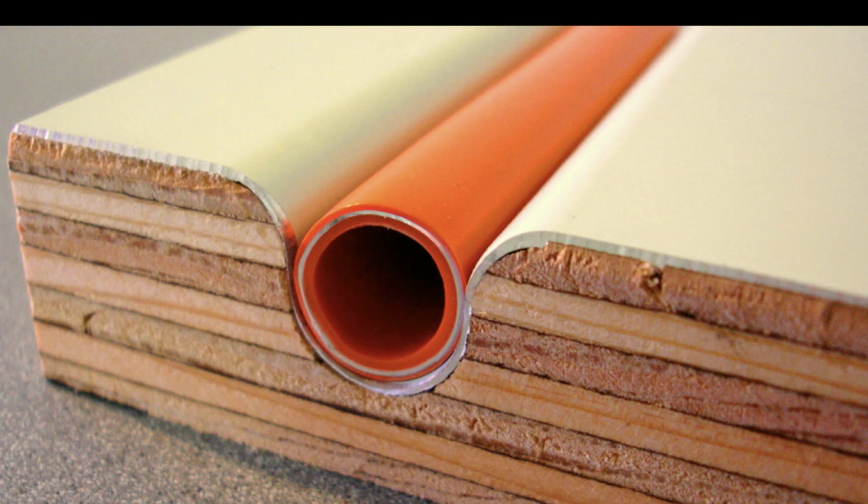Due to the fact that the supply water temperature has a maximum availability of 115 degrees Fahrenheit, the radiant floor heating system has to take this into consideration. It typically requires a higher density of tube, typically 6 to 8 inches on center if you're in concrete, or the use of warm board if you're in an elevated framed floor structure.